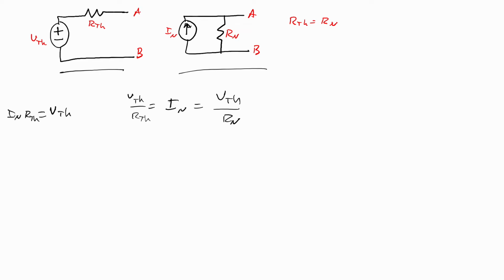Now, amplifiers, which is basically the subject of Electronics 1 and Electronics 2, although it'll take us a little while to get there, often have a voltage in and a voltage output. But transistors are actually something more like a Norton circuit. BJTs, bipolar junction transistors, and MOSFETs really act like a voltage-controlled current source, and often a Norton circuit is the better way to represent an amplifier.